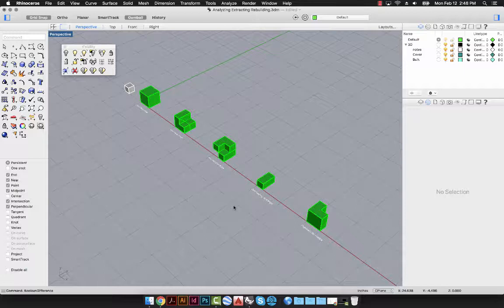So some of the commands that we just went over: the difference between planar and object snap project. We went over the object visibility palette. We went through how to select objects by type. We looked at the object properties palette in order to determine whether a poly surface is open or closed. We used the show edge command. We looked at how to set backface color. We used the select duplicates command.